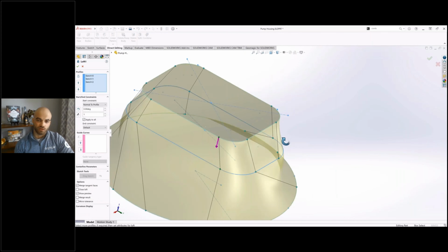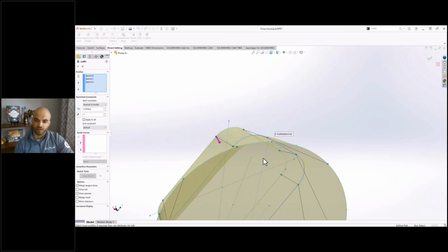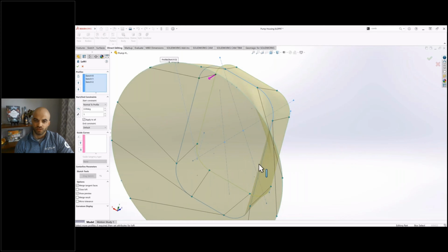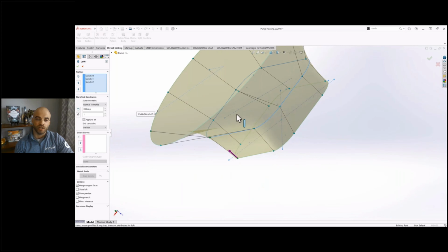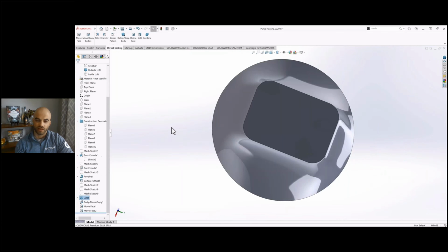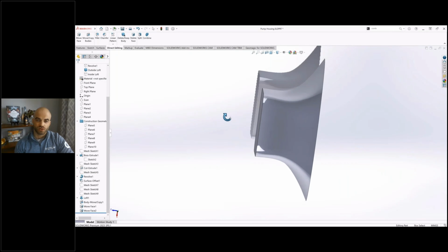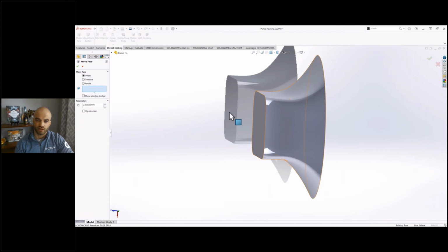And this is exactly what's going on. So even though I ate my vegetables and did the proper thing and broke that circle up into 8 spaces, it still gave a little bit of twist in the intermediate points, because when you build the loft, you just have that one control polyline, and the rest of them got swirled for whatever reason. So going in there and just fixing that up so that it is properly continuous instead of twisted allows us to do this offset properly.